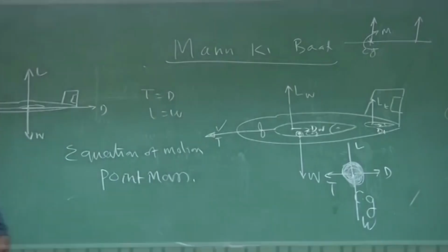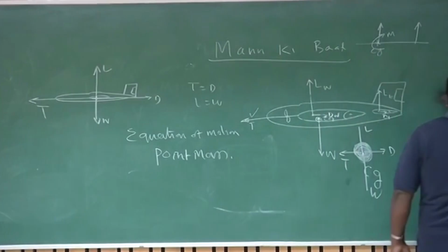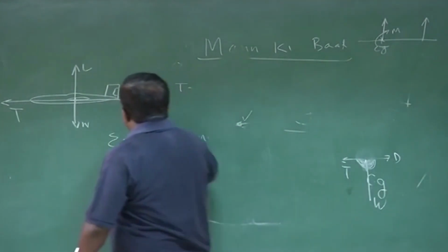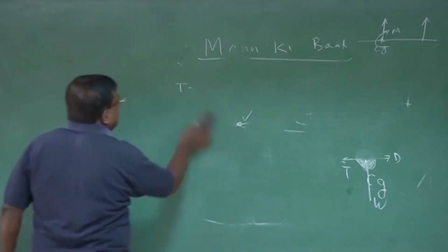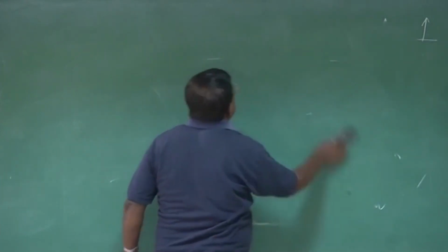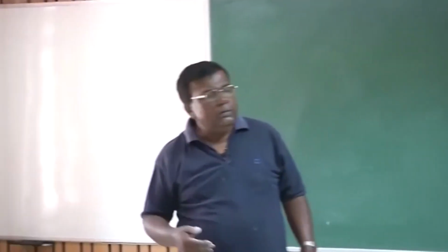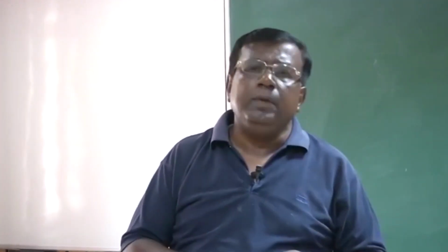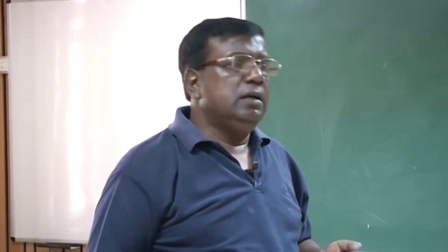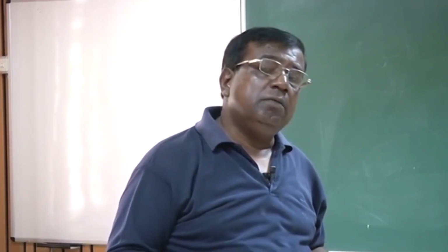Then we were also discussing rate of climb, and we have seen that rate of climb is related to excess power. But one thing I must tell you, for this sort of unpressurized airplane, aerodynamically, their ceiling or service ceiling altitude will be much higher than actually you can fly this machine for other conditions.